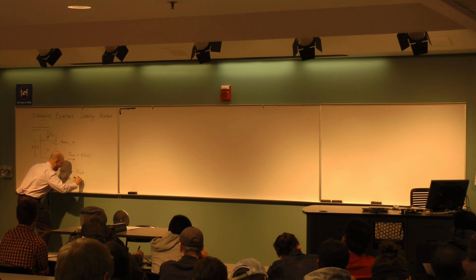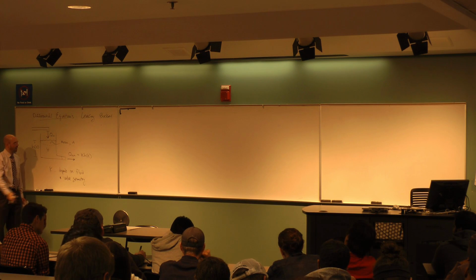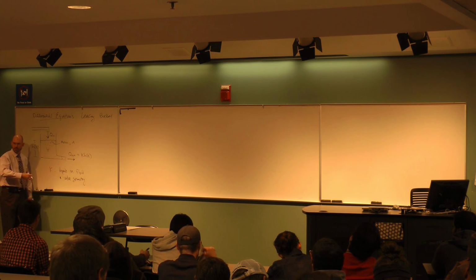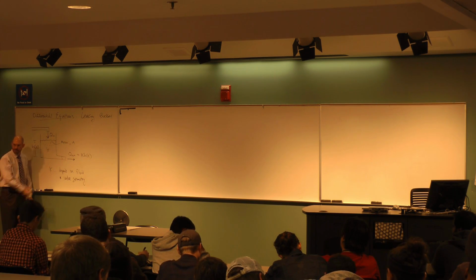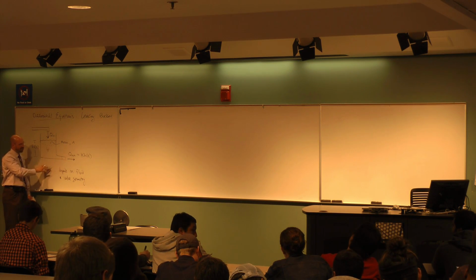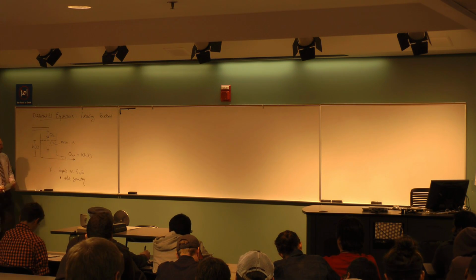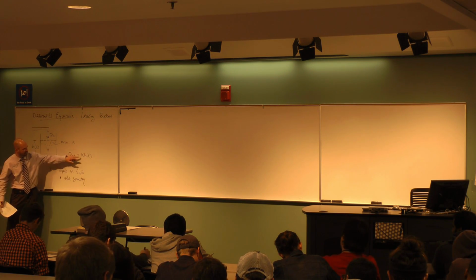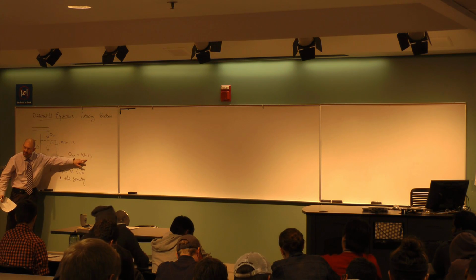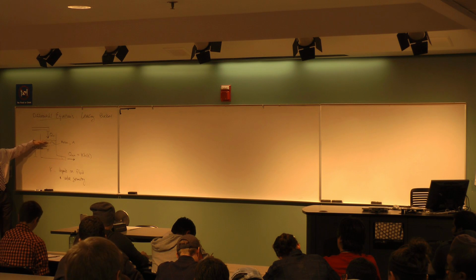geometry. Okay, and you might be able to think of other things it could depend on, like, am I conducting this experiment on Earth or on the moon, for example? That might factor in there as well. Right, so it's got to be related to the pressure, the net effect on the fluid, the valve geometry, but we will settle for the idea that the Q out is proportional to the height. Okay, recognizing that the height changes as more fluid builds up in there.